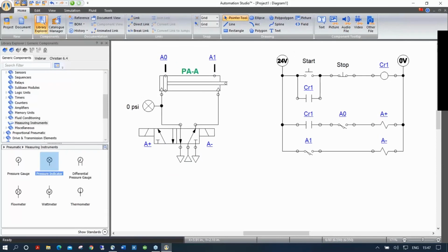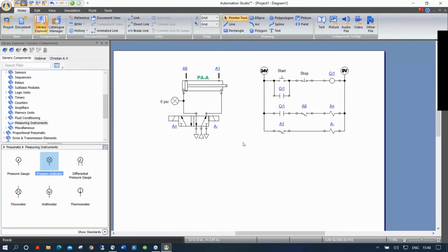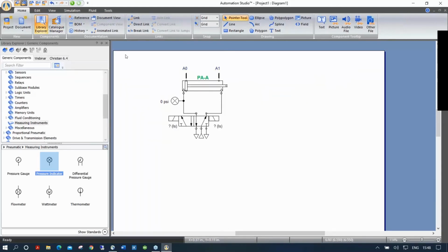And again, like I showed you at the beginning, if you want your document to display metric or imperial units all the time, you just change that in the standard, and then you save your document as a template. Let's say, for example, I'm going to do a template very quickly. I can insert a bill of material on my schematic. Let me erase this part. I think you understand what we did today here. Let me put a BOM. Just do a little square, and this will automatically generate a list of all the components that I have on my schematic.